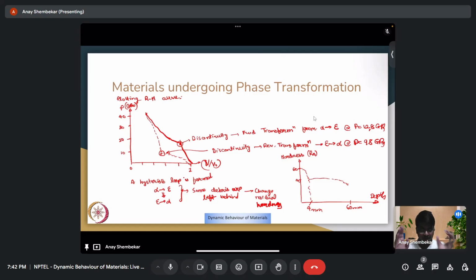They used a plastic explosive, detonated it at the surface of a steel block with a grazing incidence, not normal. The pressure that they achieved at the surface was above 13 GPa, and what that did is it would cause the forward transformation, and then as the shock wave moved deeper and deeper inside the material,